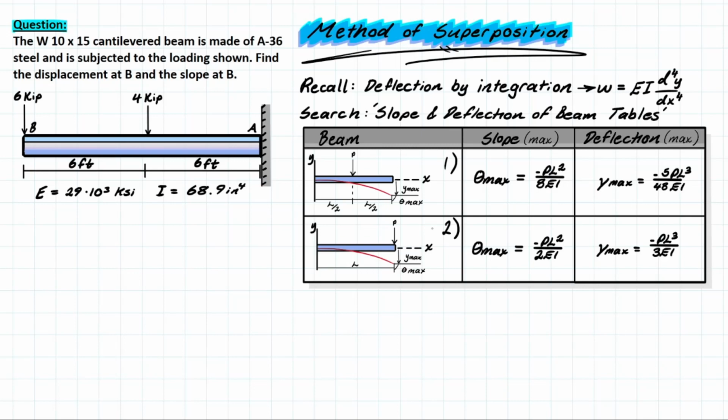Now, why do I bring up this previous video, and why am I writing down this formula over here? Well, this formula was solved in the previous video, and all it pretty much means is that if we integrate the load function 4 times with respect to x, and then bring over this EI, we can actually solve for the deflection based on that original load function, which is pretty cool. But the main takeaway from this derived equation is that the load function Wx needs to be linearly related to the deflection y. So why is that important in our case?